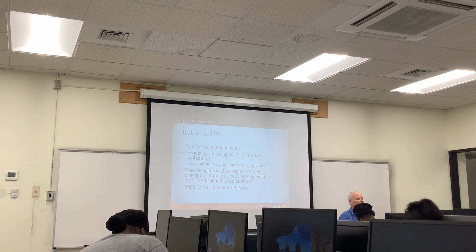Okay, rules for the IPL, they have to be truly independent. And let me ask you this, a lot of DCS systems and safety systems, they're putting in the same box anymore. I really hated that idea when they started doing that 20 years ago. I thought that was a terrible idea. Do you think it's really independent when they do that? No, I don't think so.